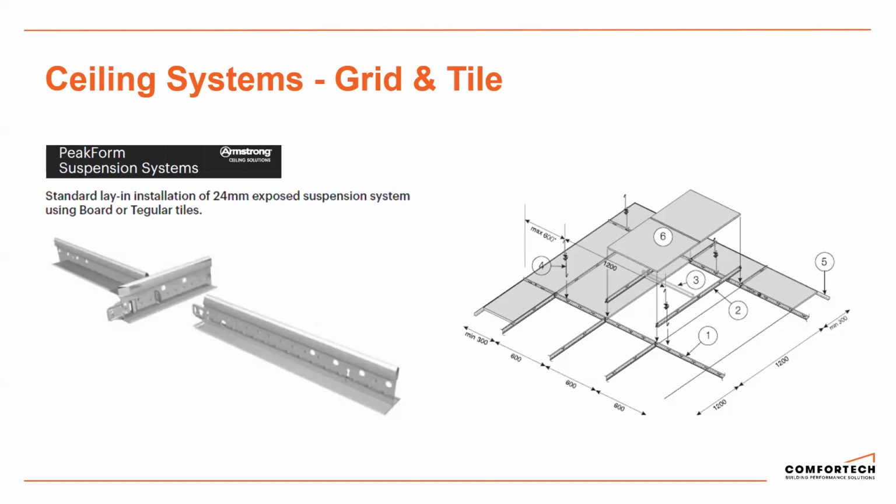There's not a lot of seismic performance difference between the two. They're made of the same material. It's just that bottom leg that's different. So a couple of little tips. For ease of install, main tees are best designed to run across the building, in the opposite direction to the purlins, so that we get good connection points for our ceiling hangers.